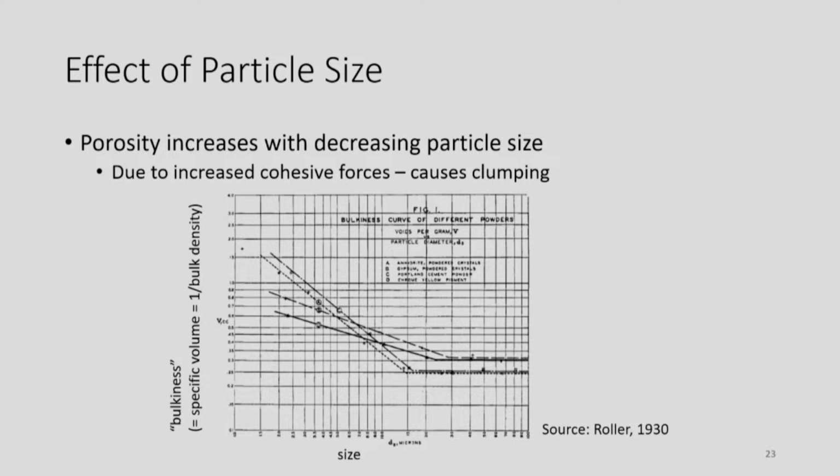Mainly, if the particles are cohesive, if there are cohesive forces between the particles, they try to form clumping or bridging between those particles. That leads to increased porosity. But if it's larger size particles, their porosity is always high, right? But again, for a smaller size, uniform shape, uniform size powder, if you reduce the particle size, in general, if it's cohesive, their porosity will also go up.